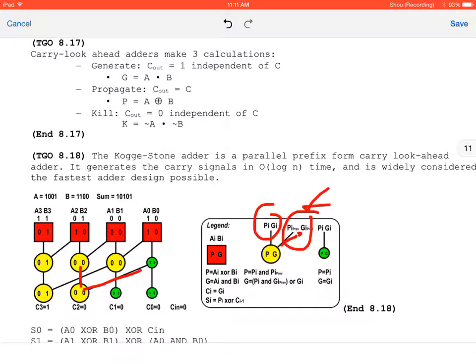So what's happening is you're generating a specific value, and then you're going to propagate the values over by a factor of log of n. So there's 3 calculations for each bit, right? You've got propagate, generate, times propagate, generate, times propagate, generate. Now these all have 0 here, and then you're going to use this to calculate each one. So let's say this was a 32-bit adder, so log n values. The first 5 would have 5 of these green propagate and generate, 4, 3, 2, and 1. And they all come out at the same time.